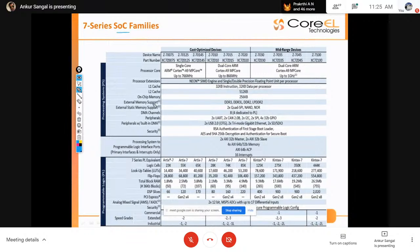With the help of this system on chip, your FPGA IC now has both options. Like if you have created some design, and in your design some portion is A and some part is B, with two different teams working. Team A designs in assembly language, and team B works in VHDL and Verilog. If you want to integrate both portions on one hardware, you can use this Zynq SoC family, because here your PS part, the ARM Cortex A9 processor, is available, and in Zynq UltraScale this is also available.